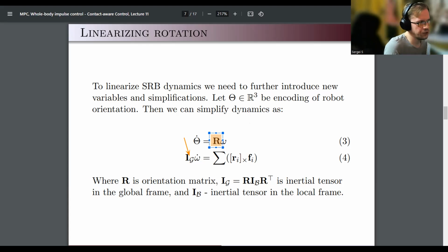This would come from a heuristic, same as the steps came from a Raibert controller, which is a heuristic, right? Same R would have to come from a heuristic. But importantly, it is constant. So this is constant, and this is constant. Therefore, this is constant. So those are not decision variables. Those are constants. They can change over time, but they're predetermined. They're not decision variables for optimization, is what I'm trying to say.